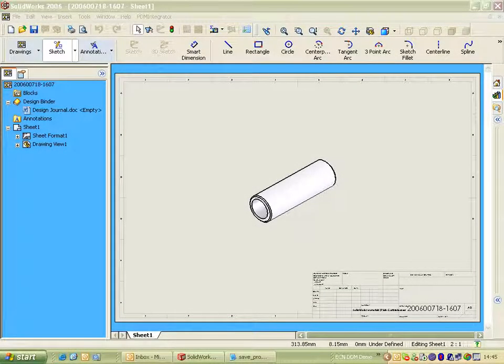In order to add custom attribute information or DDM attribute information onto the SolidWorks title block, the easiest way to do this is to create a drawing of a model that's stored within DDM, save the drawing to DDM, and therefore fill the drawing itself full of the custom attributes from DesignDataManager. If you want upissue information in here as well, then do an upissue on the drawing as well, and that will then allow all the upissue fields to be added to the drawing.